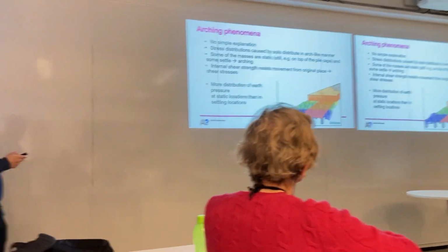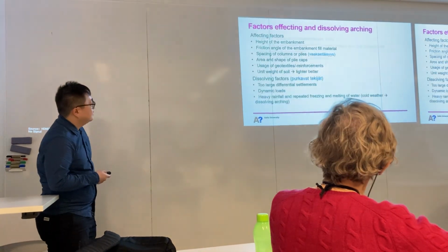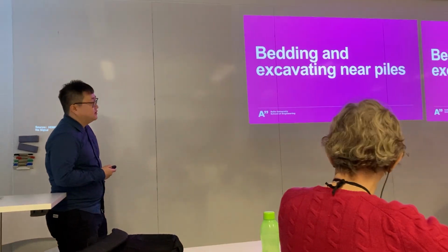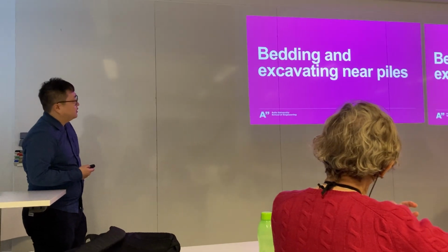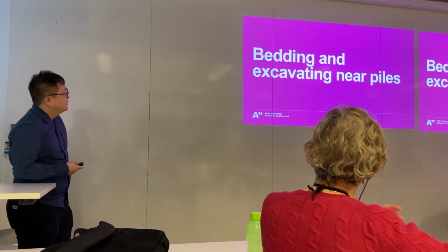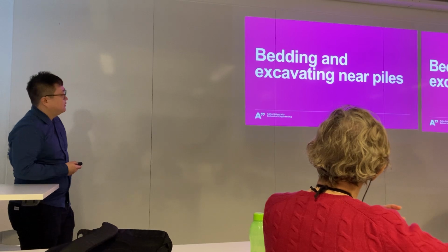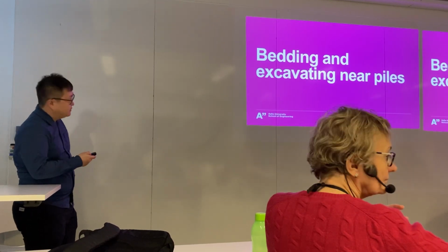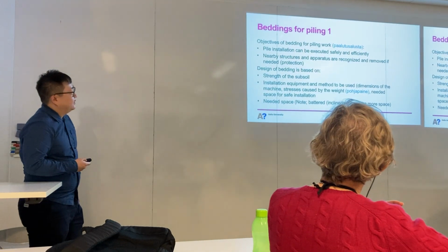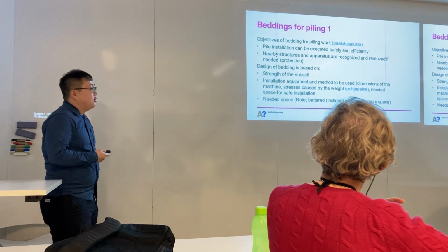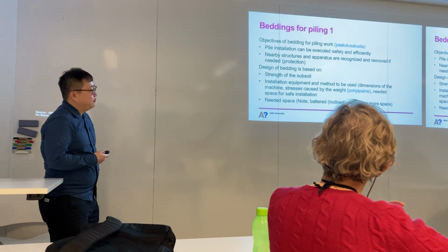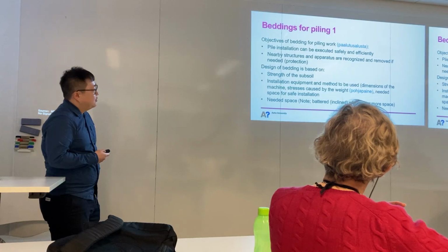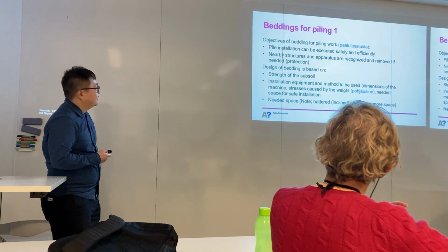Okay, thank you. So let's go on. After introducing the pile rafts and the cap structures, let's talk about the bedding and excavating near the piles. The bedding is usually made before we install the piles, and it can provide a very stable working base for the pile installation.